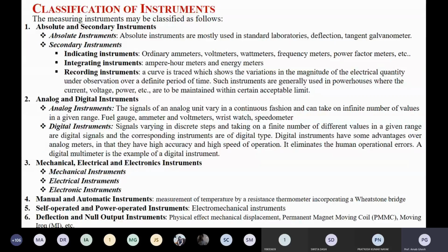Maybe I am just taking some example. If you visit any substation, you are able to see that different recording devices are there. What is your present demand? How much megawatt demand is there right now, and it is calculating all the time. It is taking the value, meaning active power. After getting the active power, what is the actual demand, what is the total generation, you can easily calculate the reactive power as well as the power factor.